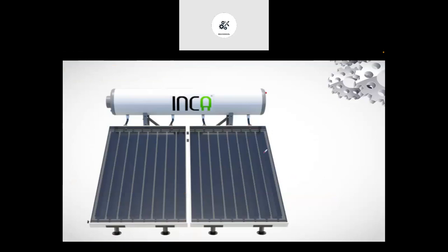Now this is the actual flat plate collector system. You will see these are the flat plate collectors, and whatever heated water is there is collected into this particular tank. The cold water and hot water are both connected in this tank. First of all, what will happen? The cold water is provided from the bottom side. From here, cold water is provided.